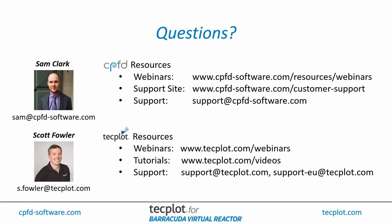And so this is one of those things that will definitely be simulation dependent. It depends on how many cells and how many particles you have going and how many results files you output. I was looking at this one yesterday just so I knew the statistics. This particular model has about 250,000 cells and something like 2 million computational particles. If I open the full 100 seconds, the load time was on the order of about 1 minute for that simulation.